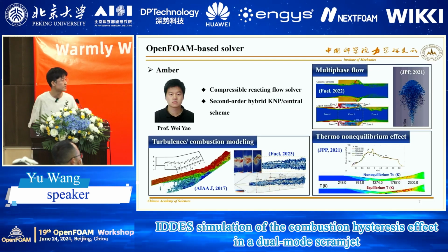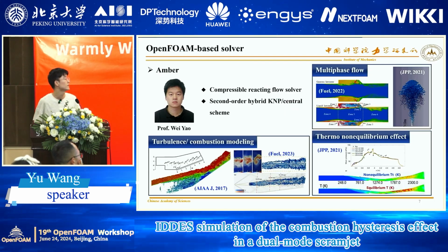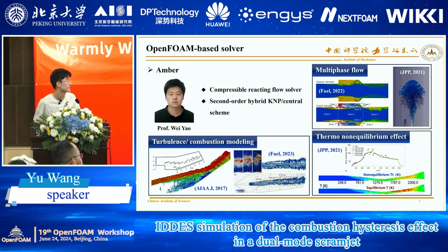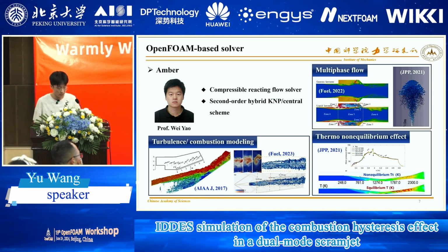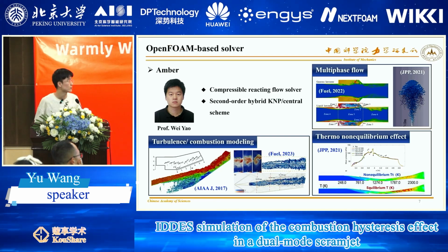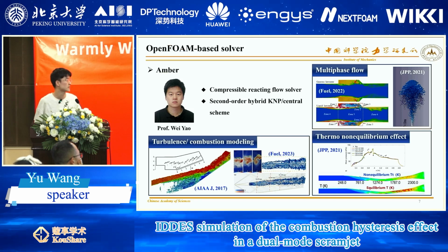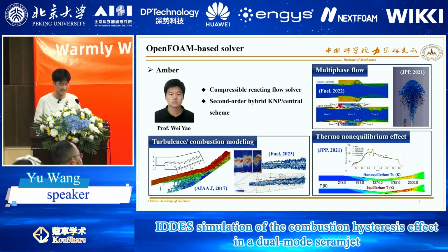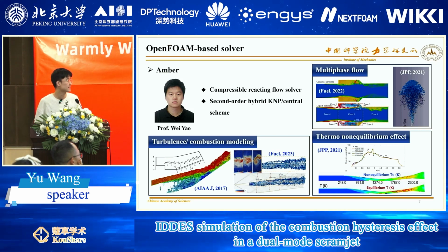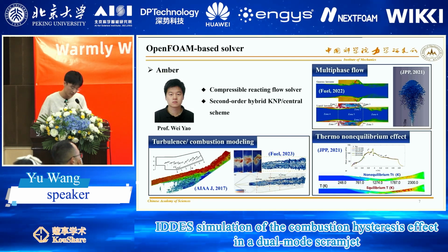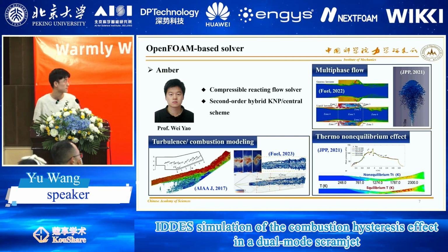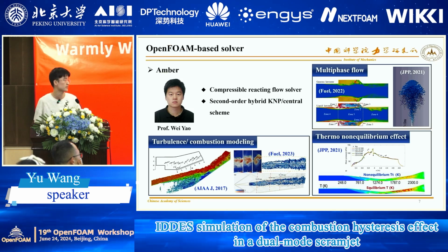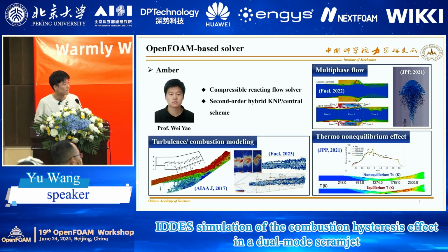The whole computation is carried out on an OpenFOAM-based solver, which is mainly coded by my mentor, Professor Wei Yao. It is a compressible reacting flow solver based on the second-order hybrid KNP central scheme. This highly integrated solver can simulate the CFD problems associated with turbulence and combustion, multi-phase flow, and thermal non-equilibrium effects, etc.